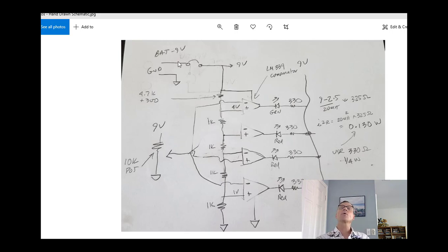So we're going to actually put these little pins on the schematic, and we're going to make sure we use the right kind of pins on the PC board, and we get them the right distance so that little shorting plug will fit just perfectly.